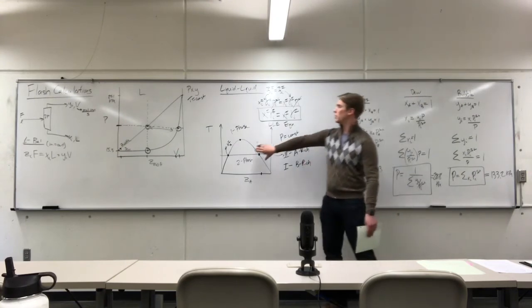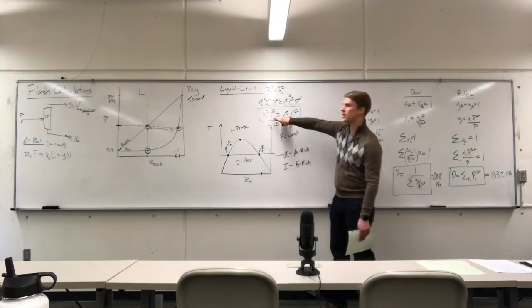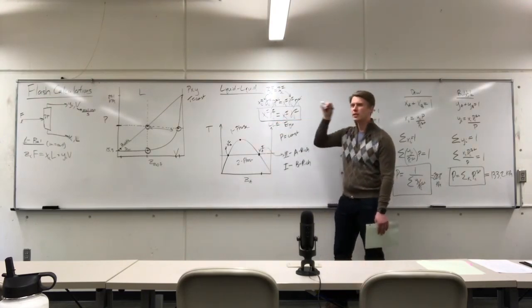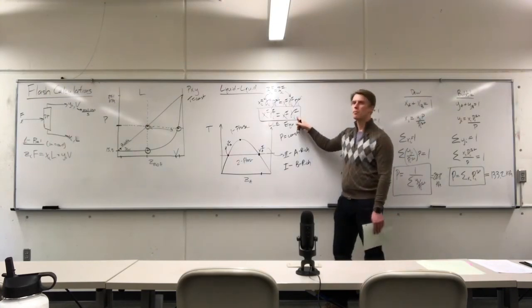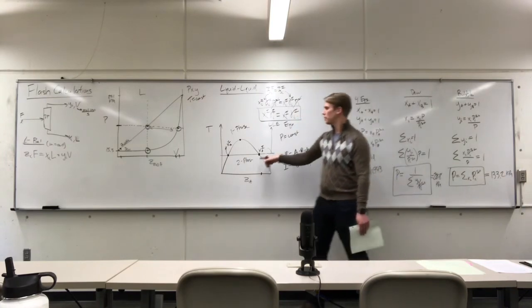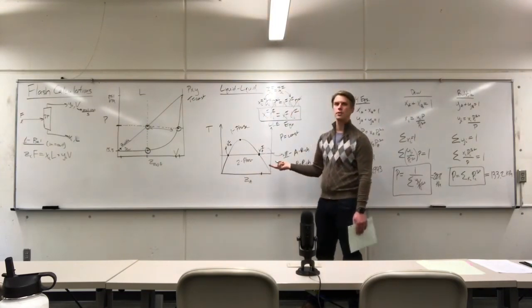Now, liquid-liquid equilibrium is really, really annoying because activity coefficient models are very sensitive to small changes in material properties and very sensitive to small changes in composition. So this really just becomes a numerical methods annoyance. But the same concept applies. I don't want to have to solve for the phase equilibrium at every single position at every single condition.